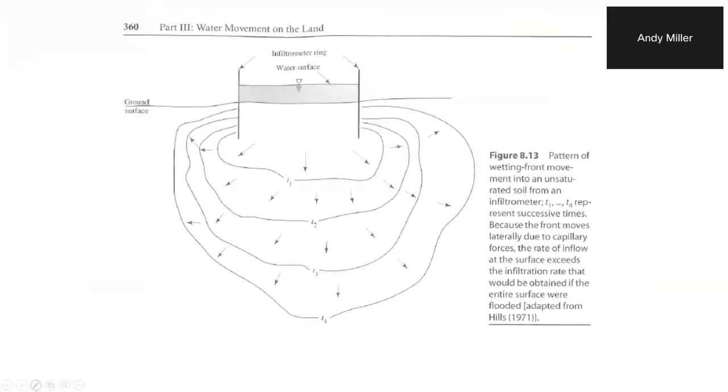And so this is a flawed experiment, right? Because if I try to wet this and watch what's going on here, and it's drier on either side, then the moisture is going to go out in that direction. I'm basically feeding the soil around me. I'm not strictly measuring what's below me.